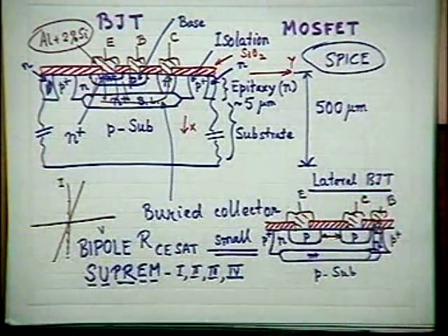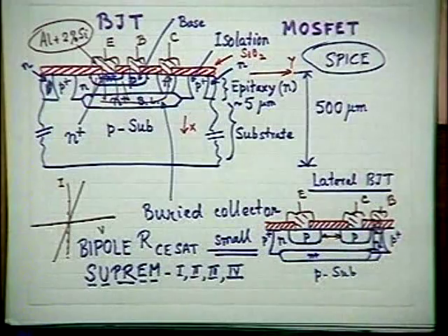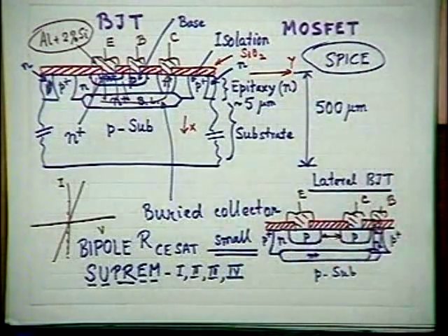There is a different SPICE, called PSPICE. PSPICE means PC compatible, for the PC under DOS. PSPICE has come, and this SPICE can ultimately be used for simulating the behavior of the whole circuit, where all the components, starting from transistors down to diodes and resistors, are simulated nicely, taking into account all parasitics. And you can ultimately get both the DC behavior and AC behavior of the circuit.